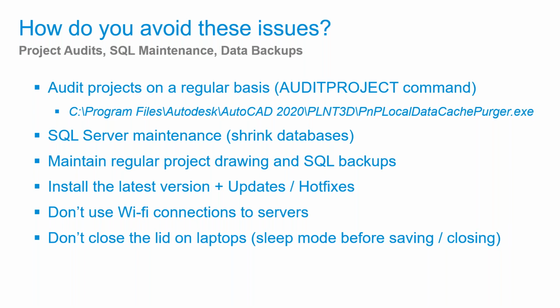And then on the SQL side of things, you can actually go in and all the way down to re-indexing the database tables. But in general, shrinking the databases is good to do every once in a while because it doesn't do that automatically. If you have a really large project, those files for the SQL databases can get pretty large. And so if you do that, maybe once a week or once a month, that will keep the disk usage down by quite a bit.